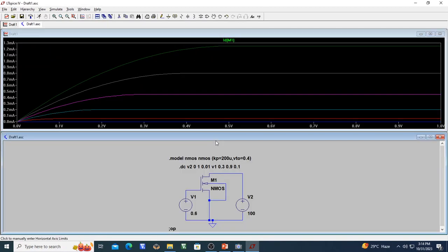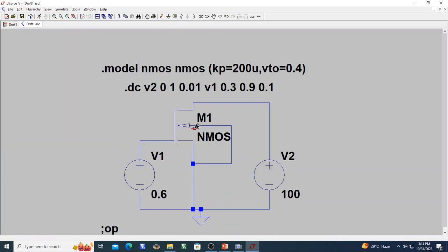Here, important thing is we should know where to get the component. It is there in this command components, and of course components you have this MOS4, and then you need to define this dot model parameter, which is using this dot op, that is spice directives. And of course I said that I want to show you the syntax. Syntax will be available here.